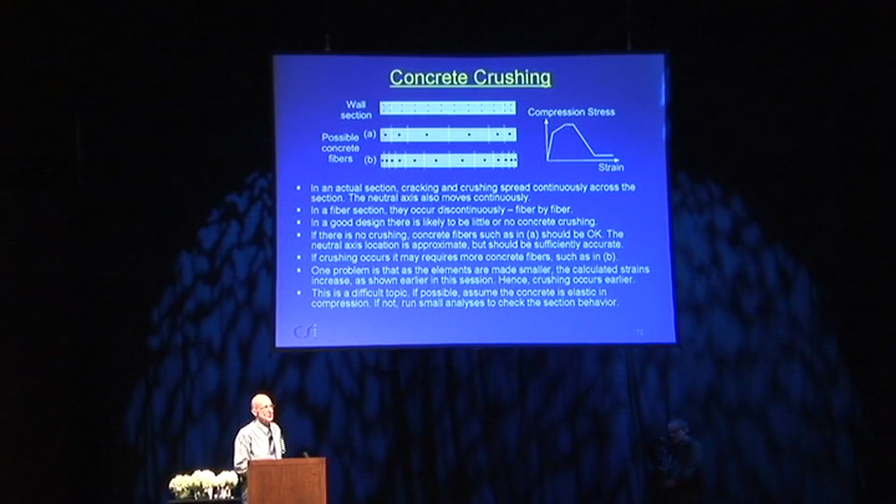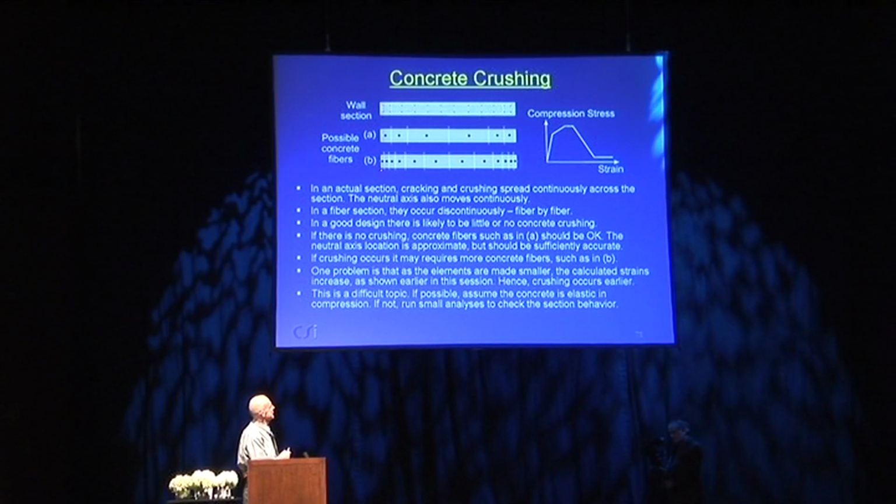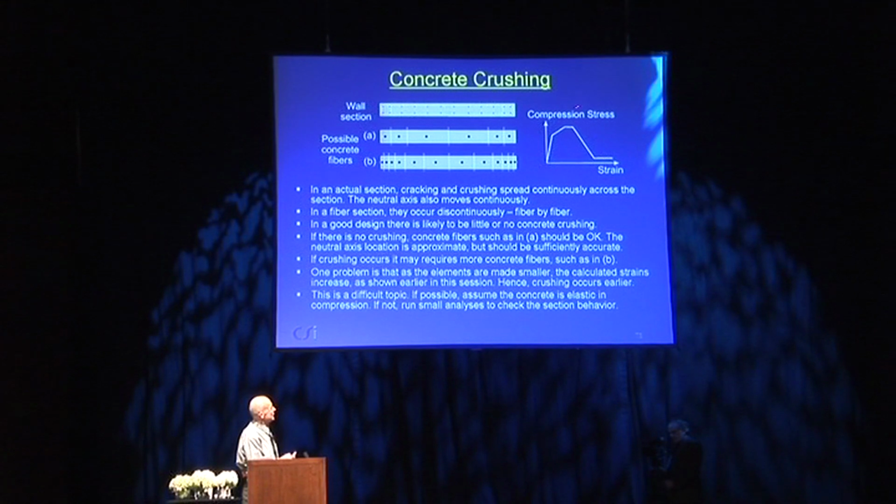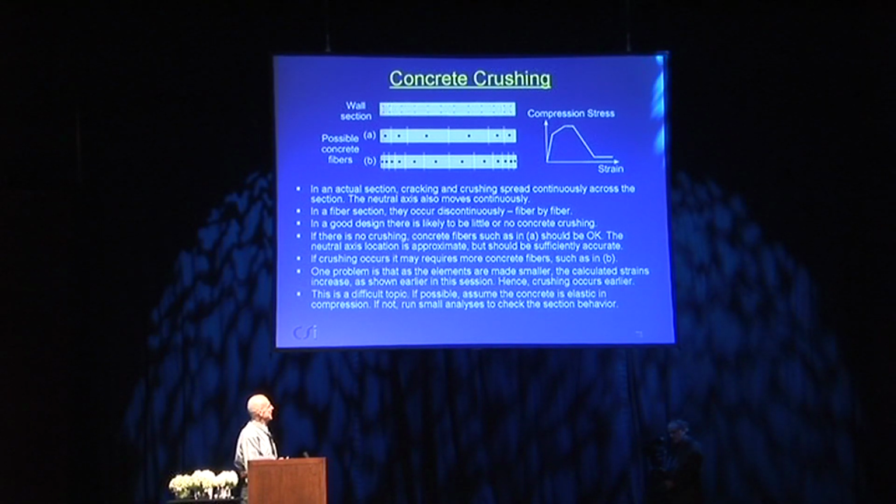Now, I would hope that you would not get very much crushing in a wall. It's not a reliable way of dissipating energy. If you do expect crushing, then you probably should use smaller elements towards the boundaries of the wall, and you probably should include strength loss in the concrete stress-strain relationship. If you don't expect crushing, you can use larger fibers, and you don't have to worry about strength loss in the concrete.